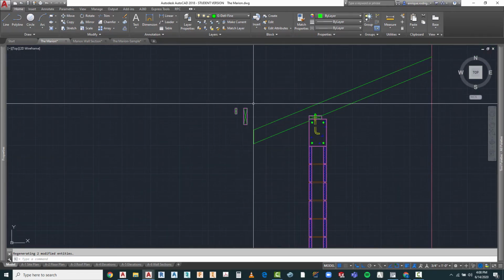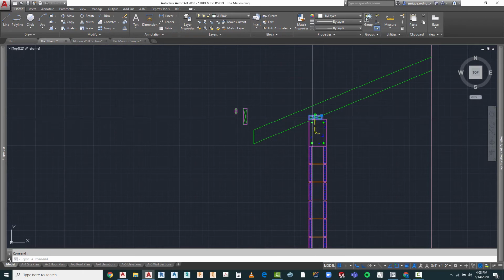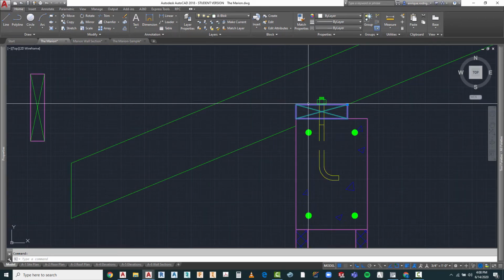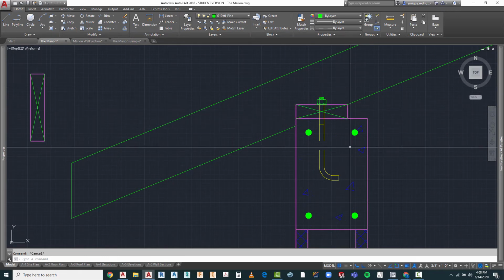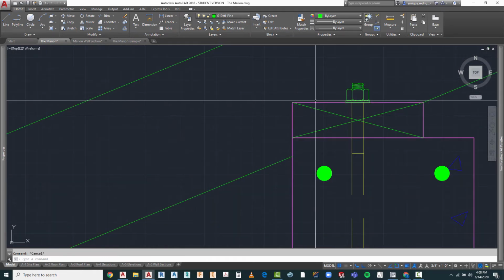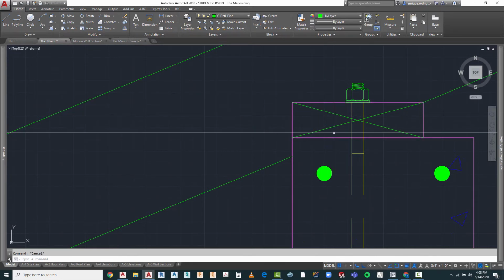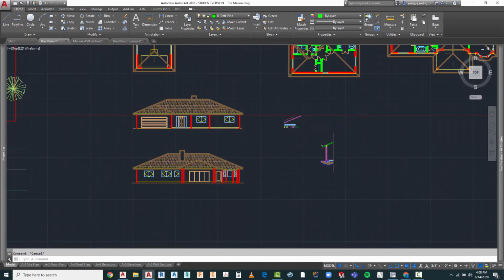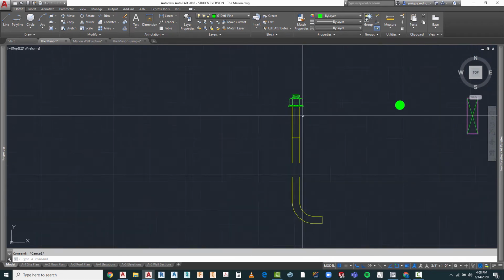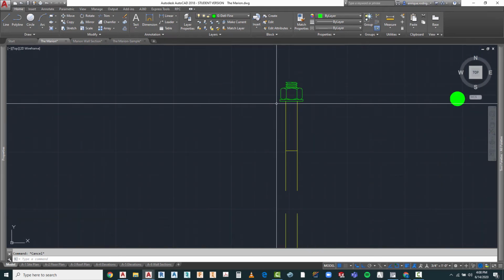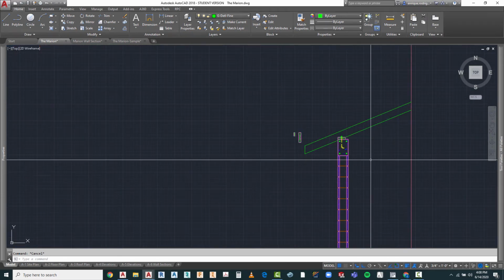We made the changes to copies of the blocks that we brought down in here. But when you make a change to one of the blocks, it should change all of the same block that you have in this drawing. So whereas before this was an A detail medium layer right here, or color, let's take a look at what it was over here. Now notice these have also changed, and notice this guy has also changed here. So that worked out excellent in terms of being able to use it.